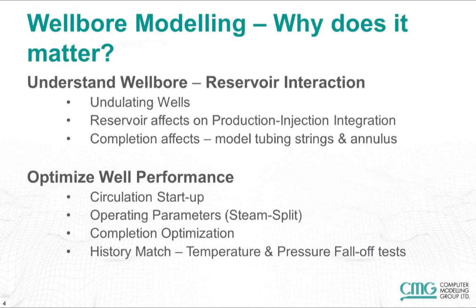So why model and optimize the wellbore? It's important for us to understand the wellbore and reservoir interaction, as it can have a profound impact on the production profile. Consider undulating wells, where liquid loading and slugging or fluid segregation can have an impact on the production profile, or thermal processes where the heat transfer between tubings and the reservoir can impact the thermal process and the recovery itself. Simply put, the wellbore is the interface through which we interact with the reservoir. And hence, for us to understand it better, we need to be able to model it. And if we are able to model it, then it presents an opportunity for us to be able to optimize it.